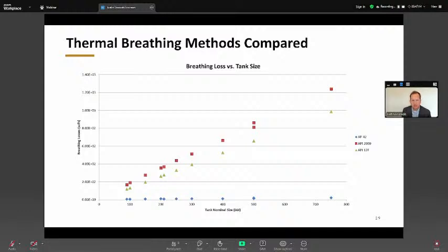because that's such a steep line. And really what this comes down to is engineering judgment, field validation, because we know thermal breathing is not going to be AP 42, basically zero, which is an older legacy approach for EPA. And API 2000 is highly unlikely. That's extremely conservative. But if you run API 2000, our regulatory agencies will accept it, but it might require drastic oversizing of your control device or your vent system. We know it's going to land somewhere between those two. And that's where the field data, tank pressure monitoring, and validating your model to what's happening in the real world is absolutely crucial.